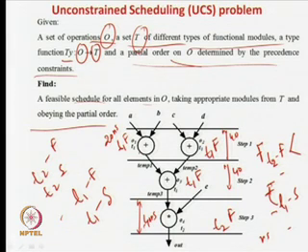So, I am putting in the fastest multiplier available, which is 40. That means I cannot compute multiplication in less than 40 nanoseconds. So, I cannot bring the time step down below 40 nanoseconds. There is no use of putting in a very fast adder over here, because even if I get the solution in 20 nanoseconds, I still have to wait for 40 nanoseconds.